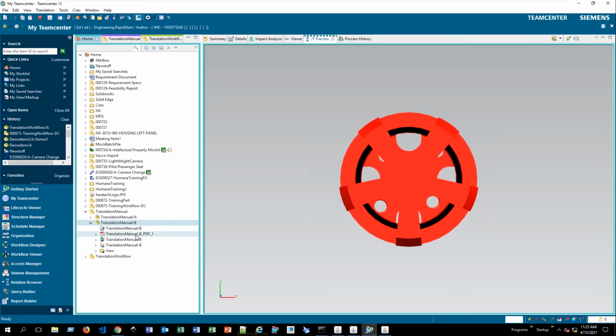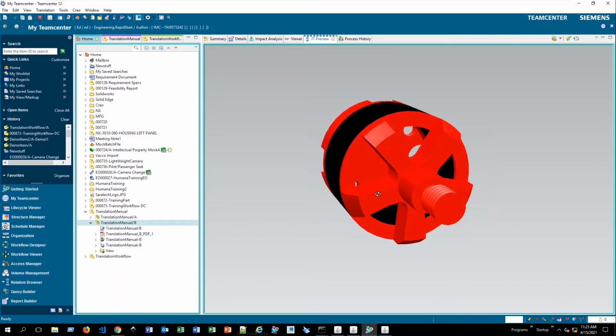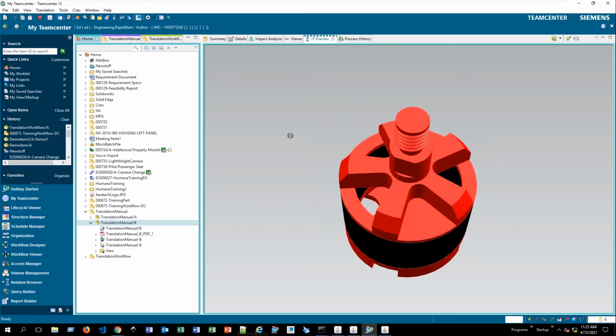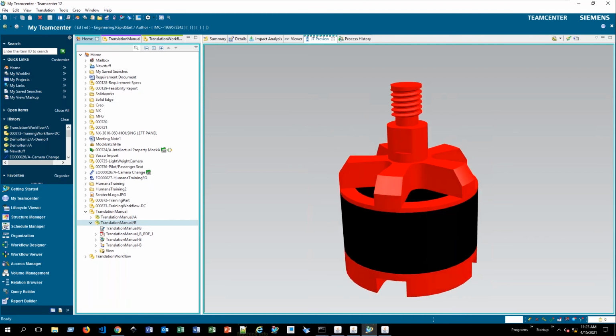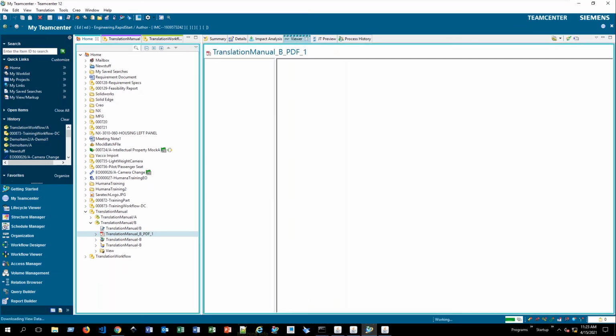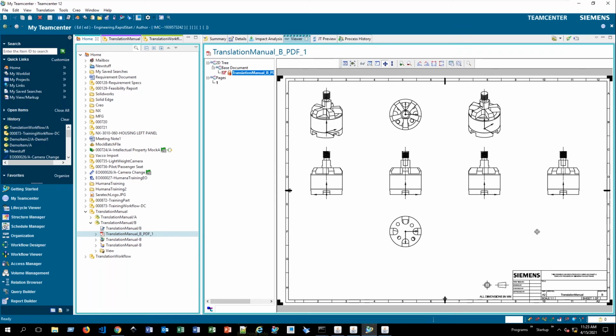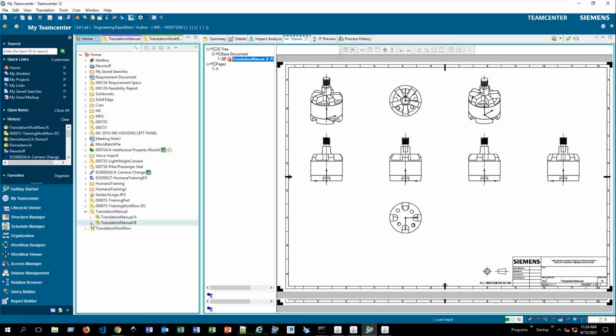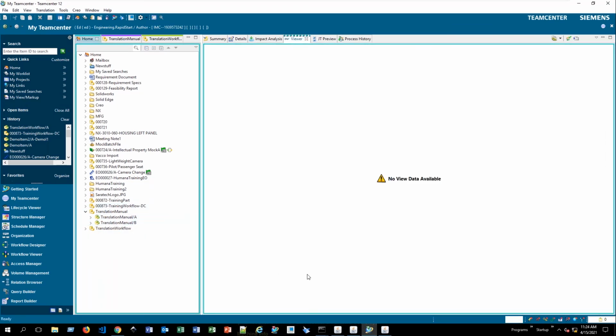And we can see we've got our PDF as well as, again, our lightweight JT file, this 3D model here for me to manipulate and query right here within Teamcenter, directly correlated to my NX part. And additionally, what I have here is my PDF of the drawing sitting there within NX. So just that easily, just that quickly, I was able to run that translation.